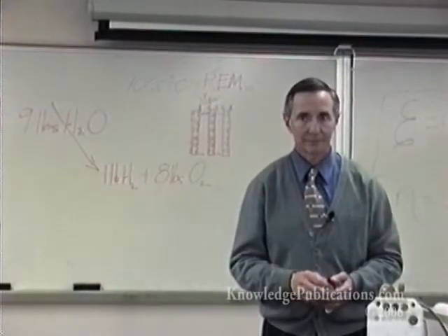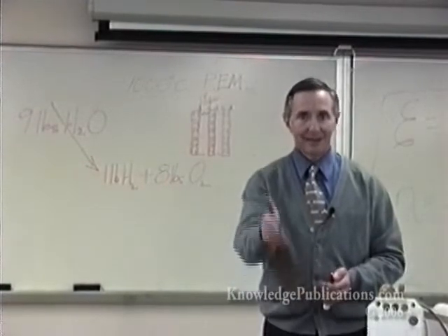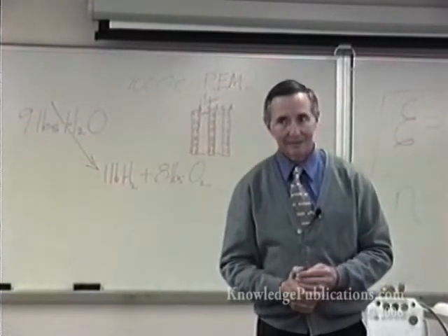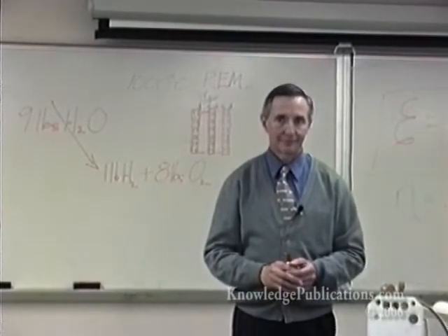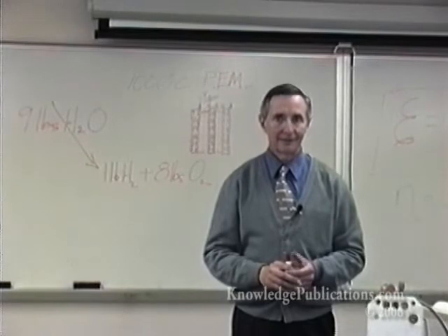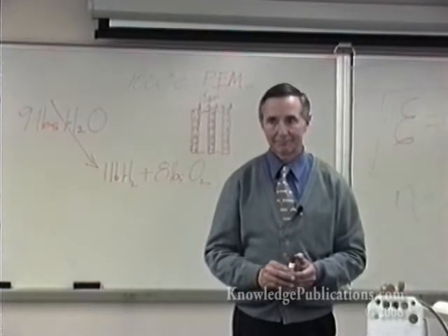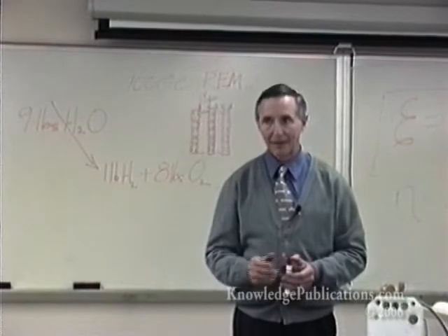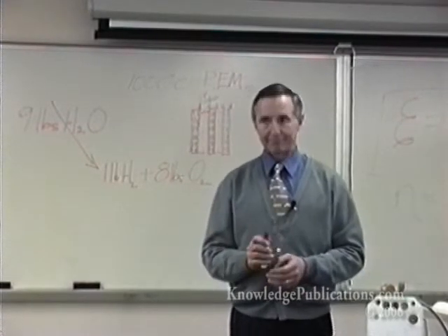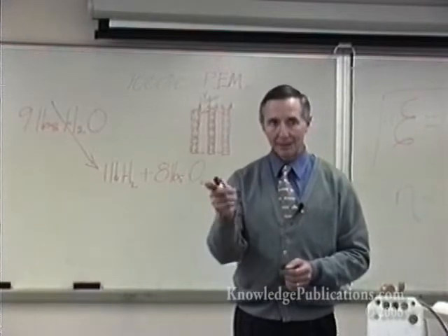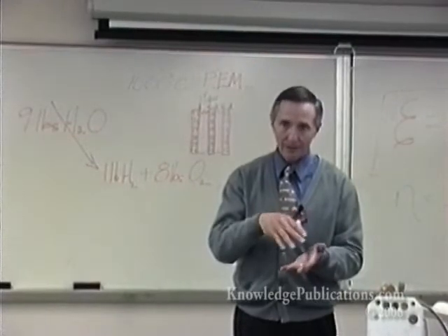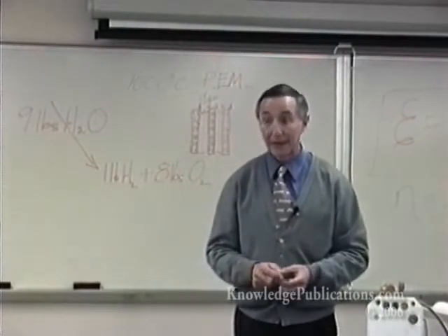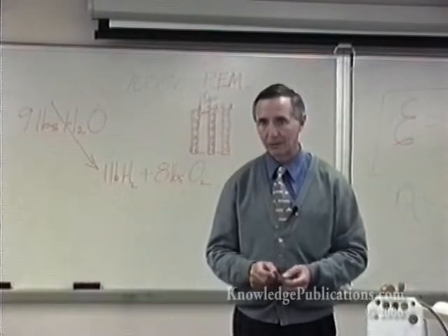Well, I can tell you, there's basically not much airflow around the muffler. At 60 miles an hour, take a vehicle like a van, put a clear glass floor in it, and put streamers down there. There's hardly any airflow around the muffler, a couple feet per second. However, if you put it on the radiator, it's like 8 times the amount that you would actually take into the internal combustion engine. It is that, but the temperature is so much lower that the rate at which it is converting is about 1,000 times less. Yeah, it turns out to be way downscale.